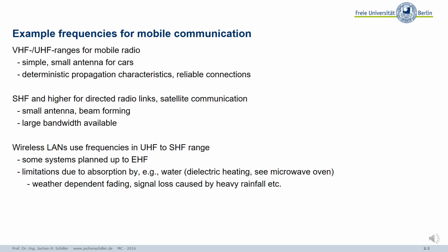Okay, so these are the frequency ranges that I just explained, like what we use here for wireless LANs. And also you see what we can also use here for the microwave oven. Yeah, that's also at 2.4 gigahertz. Even though you have nicely shielded microwave ovens today, if you switch on the microwave oven and you have a wireless LAN close by, there's still a lot of interference.